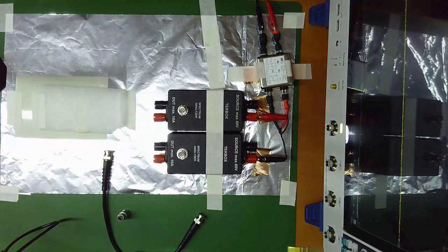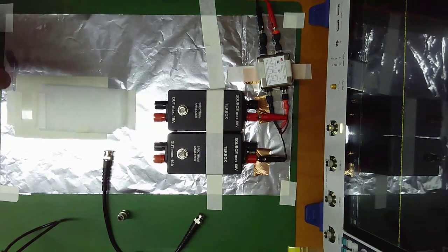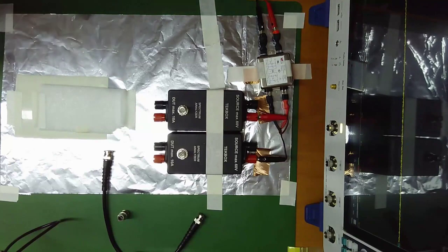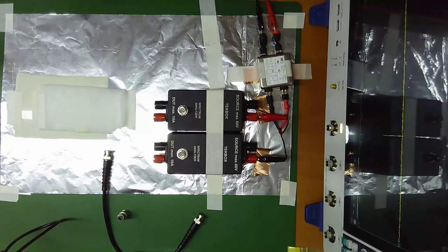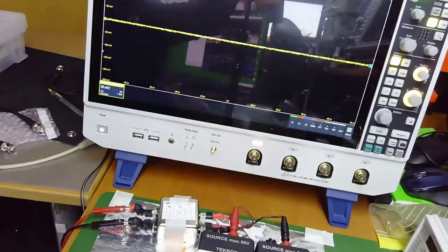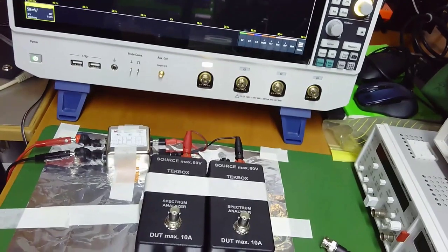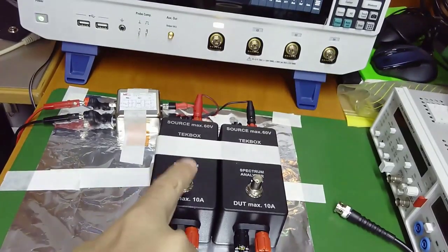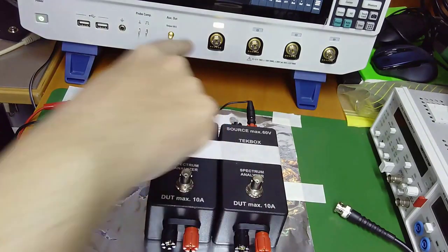You want to see how is the setup, we can switch to, let me show you here. Let me change the angle of the camera, and you will see that close to the line impedance stabilization network, we have the oscilloscope. Here is the oscilloscope, and I will be connecting the output of the LISNs to channel number 1 or channel number 2. Oh, sorry, I didn't change the camera. You can see here, okay? So you see here the oscilloscope, channel number 1 and channel number 2 will be used to measure the output of the LISNs directly, okay?